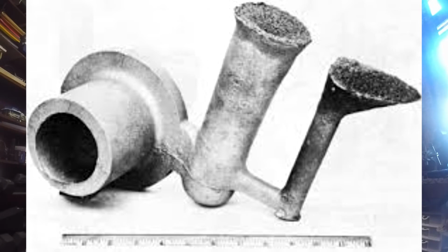Looking at this, it looks like they did a good job on feeding it, but they still didn't make a good gating system, because even though the sprue looks like it's a little bit tapered, and they made a nice pouring basin, down in the bottom underneath the sprue they don't have a splash basin.